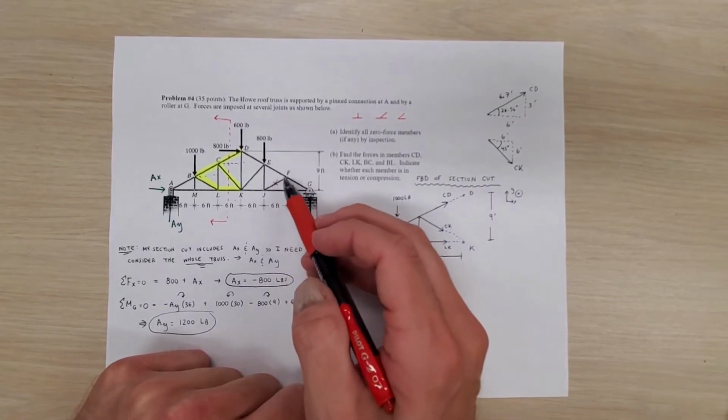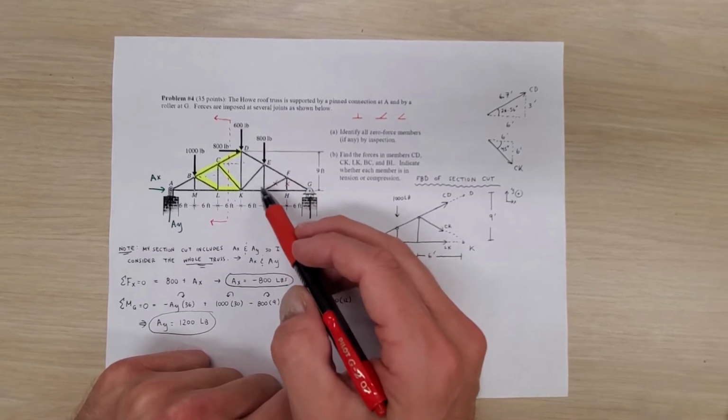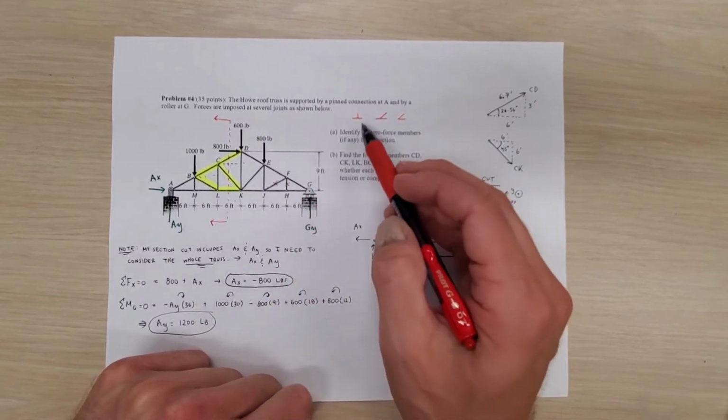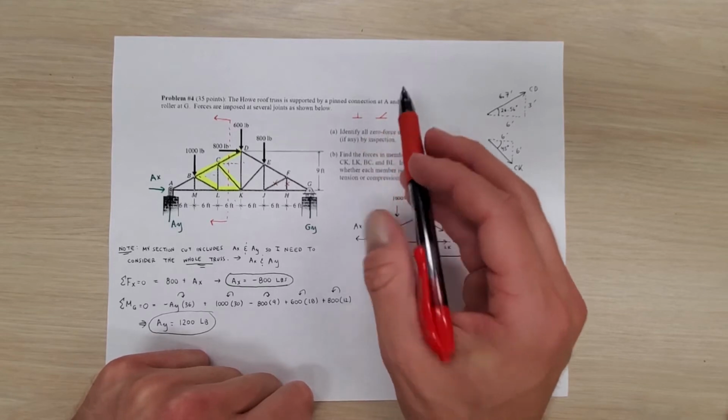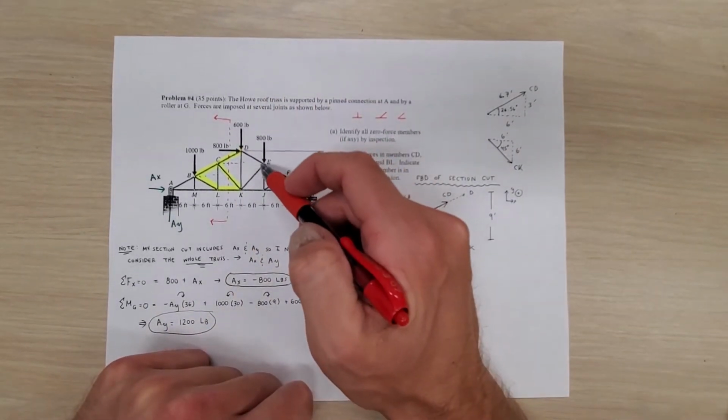And then if that was a zero force member, another domino falls, which is EJ, because then this member will be linked with the bottom of the truss as in method 1, which is the T. Therefore, EJ is a zero force member. I can't rule anything out at E.